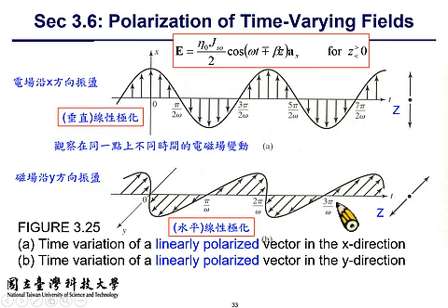As long as you know the description of the electrical field intensity, you can use the cross product of the propagating direction crossed with the E field and divide it by eta sub 0, which is the ratio between the E and H field.